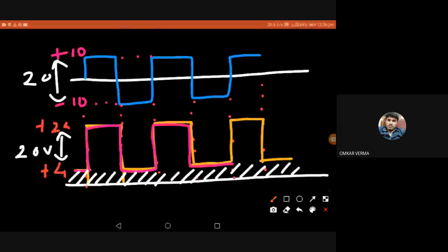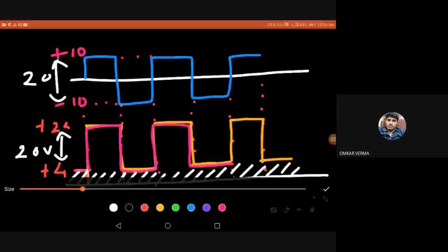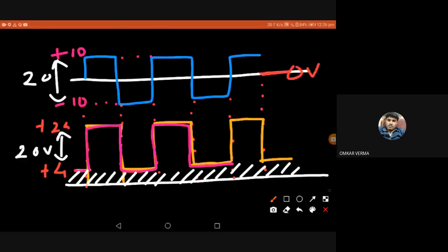Right? Initially it was the ground. You can see initially the ground was at 0 volt. Now, where is my ground? For the symmetrical circuit, it is at 14 volt, with 10 on top towards 14 and minus 10 towards the bottom also. So I gave a DC shift of 14 volt because my DC voltage VB was adding to the capacitor voltage. Is there any doubt about what we have done? The shape is remaining the same, but there is a DC shift.